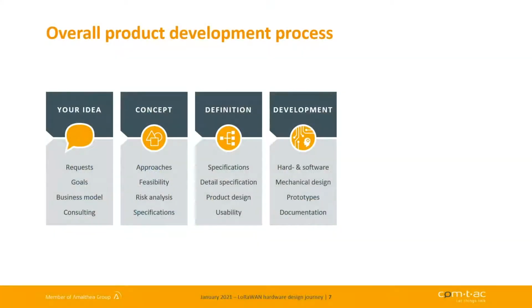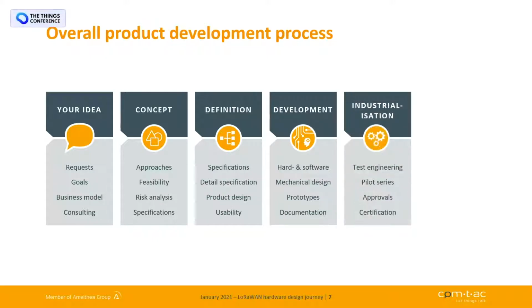Then we really start with the development of it. We make the schematic and layout, we build a prototype, write firmware and test it, and we go to certification with the device. If that's already done, we have to think about industrialization, because you of course like to have a big number of devices in the field, and you need a test adapter and all the things you need for production.